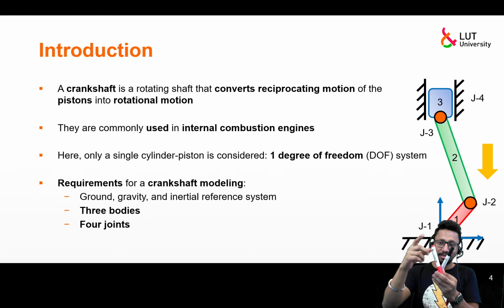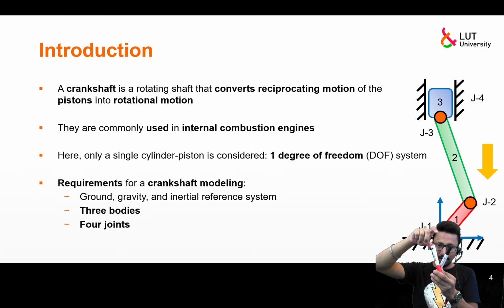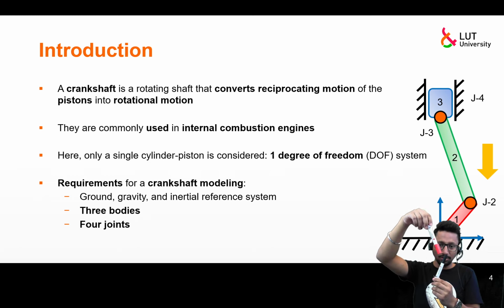And also if there's a revolute joint here with which it is connected to the piston, it is also going to rotate like this. Now for you, it's not necessary to have a connection between these 2 points using a revolute joint only. It can be replaced by any other joint so that you can take care of the mathematics, and this is what we will see in today's tutorial.